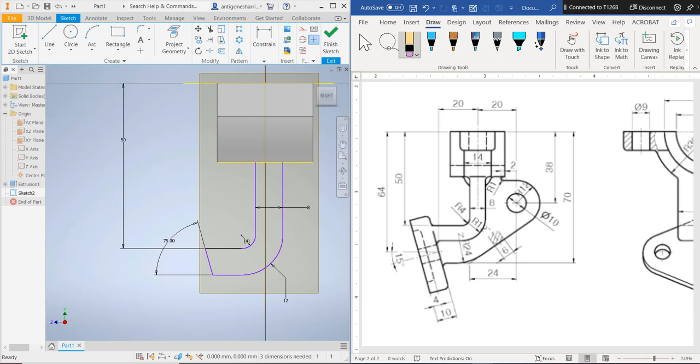Later on, you're going to put a note in your detail drawing to verify that the neck is centered. Okay? Please verify that, because this drawing does not perfectly tell me that. I am guessing. That's what assuming means. Technically, I'm guessing that the center of this to here is 4. Do you hear that? And therefore, I'm guessing that this is a particular distance from the end, too, correct?